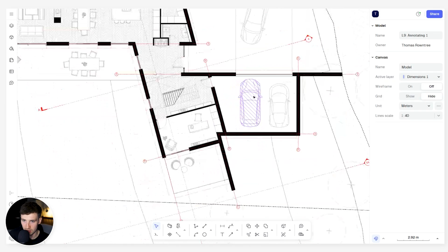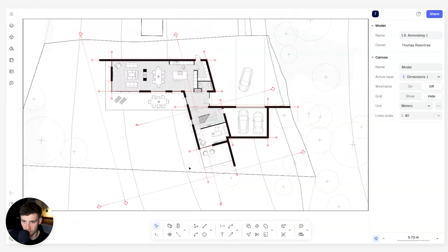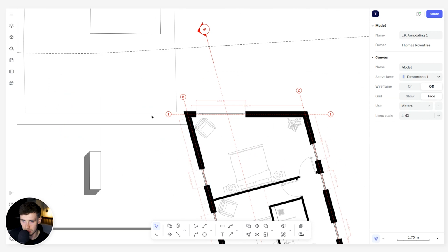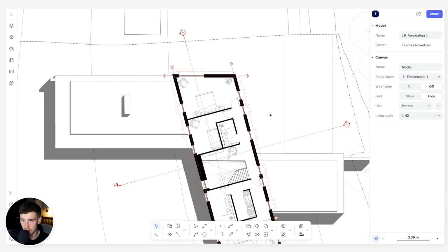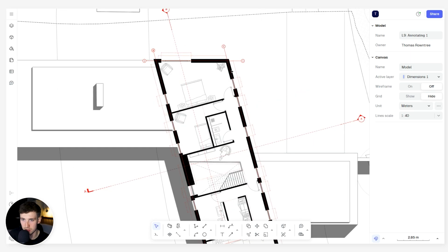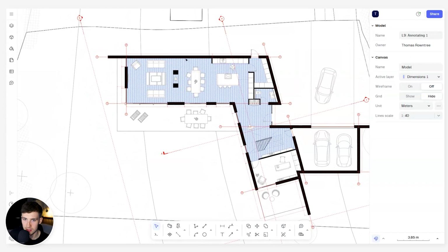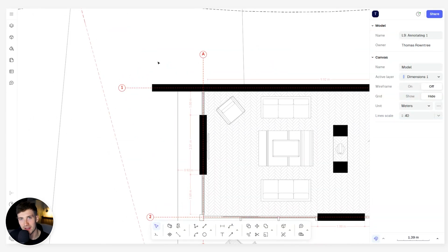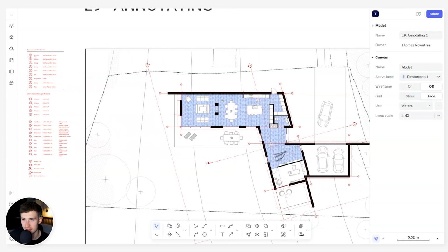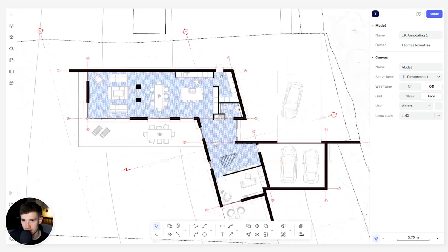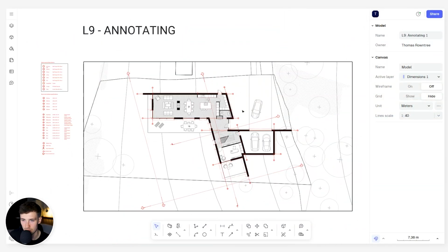And as you can see, we've now got a logic that you can refer to when you come to the upper floors. You can see that we've got 1, grid B and C aligned. So when you're referring to certain components, you could say grid C1, and it's also a nice graphic addition to the drawing. I like having a number or a letter addition with the circle head. I think it looks nice and it gives the drawing a bit of order.